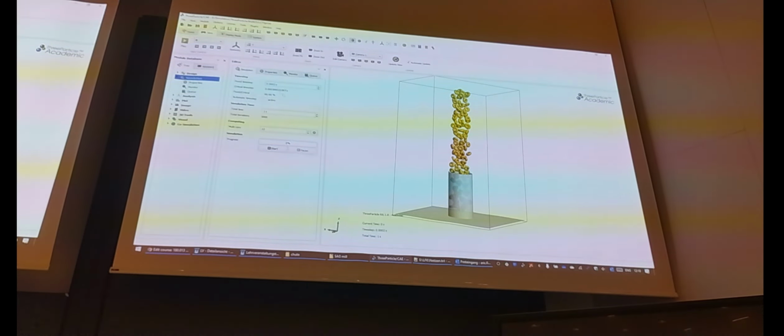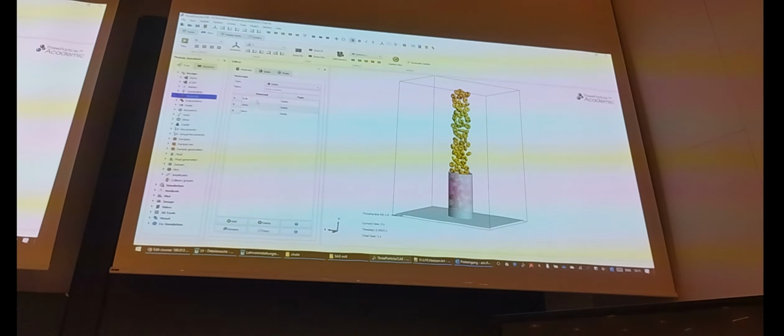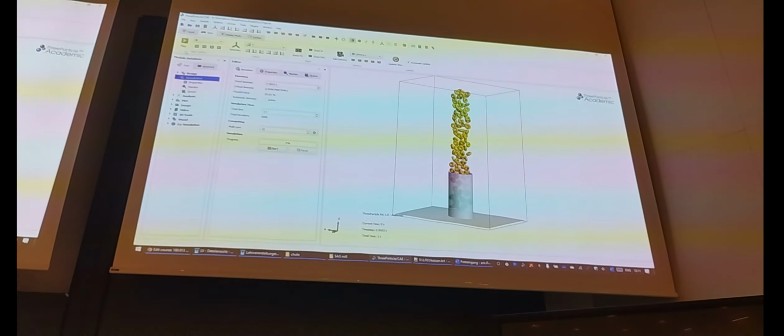When I decrease the shear modulus to 10, this goes down to 30%. Okay, materials, bulk, I changed that here, 50. And only for one material, not for the three materials. Yes? So, save, 30% and hopefully safe, let's see if it works.